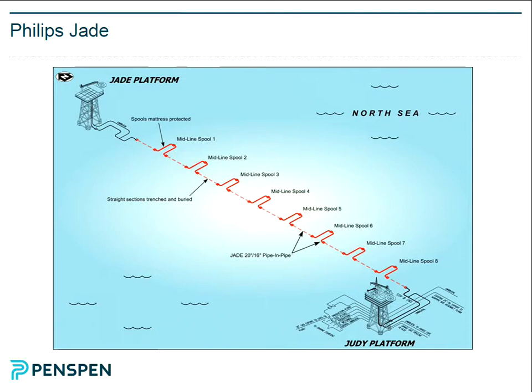And obviously, because it's very hot, it generates enormous axial loads, and the way they deal with that is to put all these individual spools in to accommodate the thermal expansion. So it's quite a robust solution. So this is the opposite situation to the LNG line. It's very hot as opposed to very cold, and these are to remove the very high level of axial tension. So very challenging pipeline, very expensive, very critical.